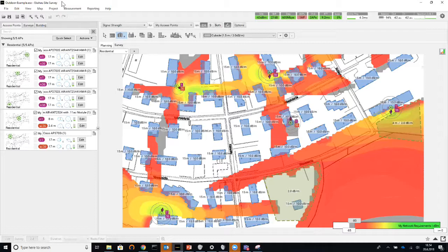You could. Again, every vendor's algorithm works differently, but universally, most vendors are trying to maximize the SNR, so maximize the RSSI between one hop and the next, and they're trying to minimize the total number of hops. They may be optimizing other parameters as well.